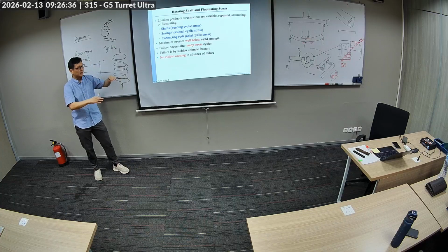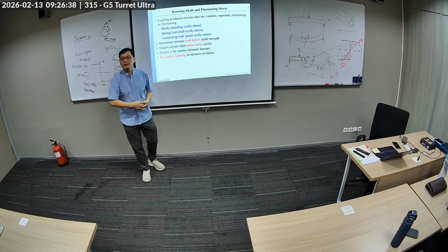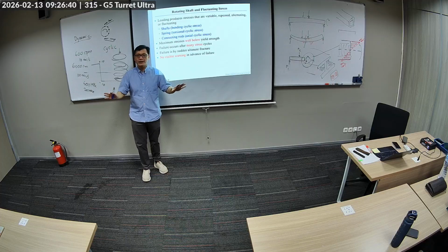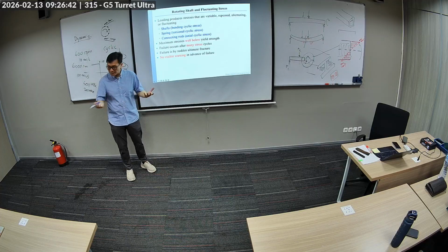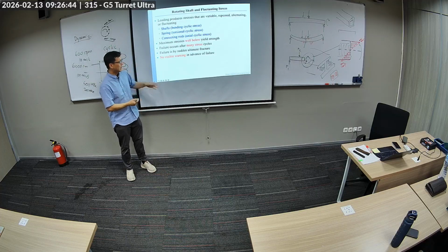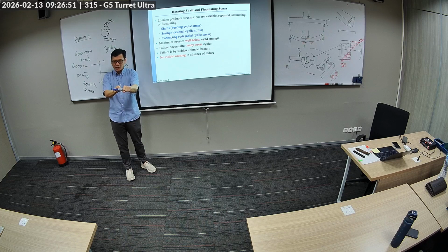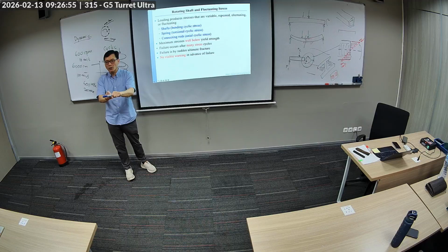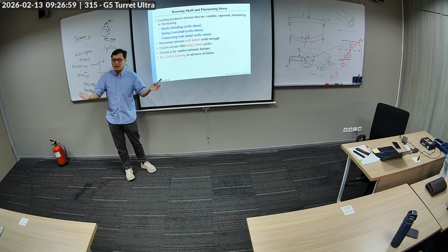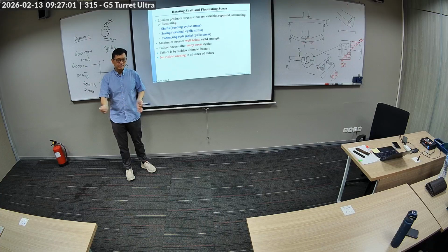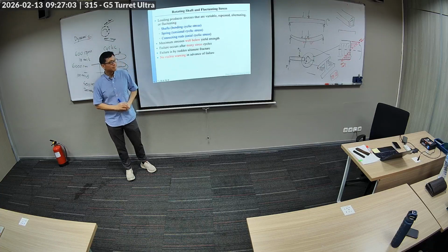Dynamic or cyclic failure, because of these many stress cycles, it actually fails suddenly. So it breaks. So it becomes catastrophic in nature, right? And there is no visible warning. Because when you cycle this, there is a crack. You cannot see it. It's only microscopic. So there is no way we know right before it fails. Suddenly, at 150,000 cycles, it just happens.